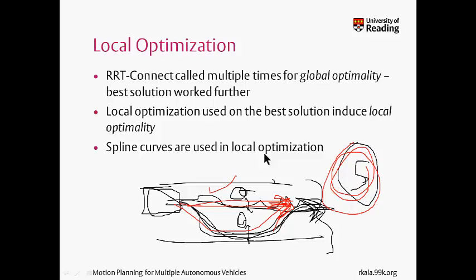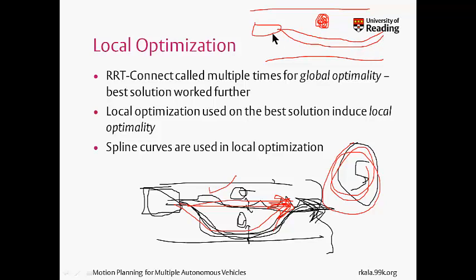But this only solves a part of the problem. The other problem is that RRTs are not locally stable as well. So let me instead say my scenario was like this: my vehicle here, my obstacle here, a small obstacle here. The RRT cannot decide between this path, this path, this path. And by the way, because it is RRT, they generate very funny solutions. It will generate these kinds of solutions.